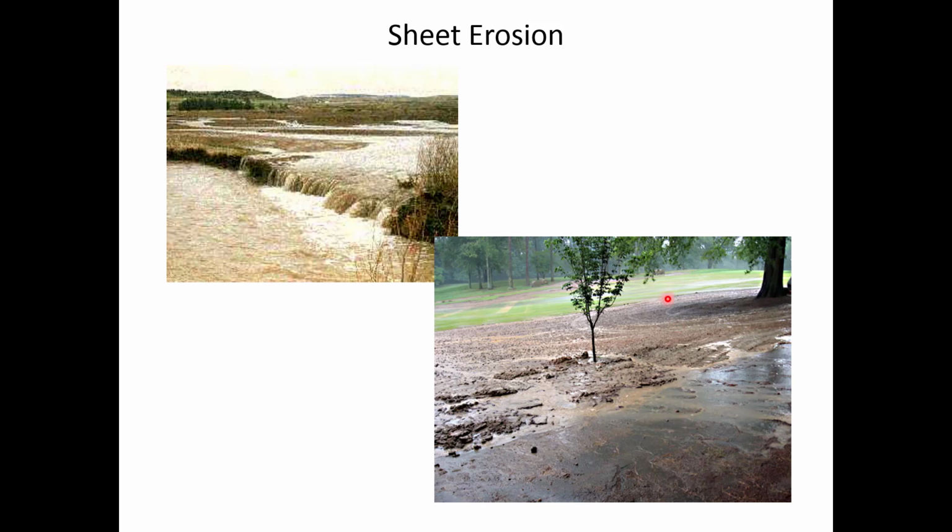We'd much rather that this rain infiltrated, recharged the groundwater, and seeped out gently over the next years to feed a stream. What's happening here instead is that the rainfall is hitting the ground, not infiltrating, running off, taking its energy, picking up soil, and dumping it into the creek. And when we look at hydrographs, we'll see that the creek will then rise quickly and drop off, which is not helpful for a good creek habitat. The creek would much rather have slower flow seeping from groundwater and steady flow.